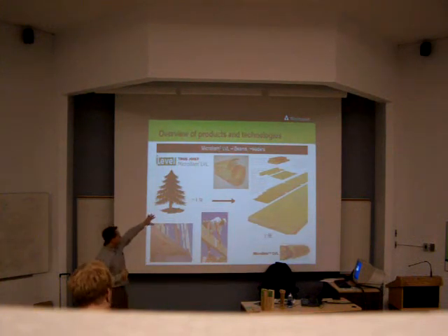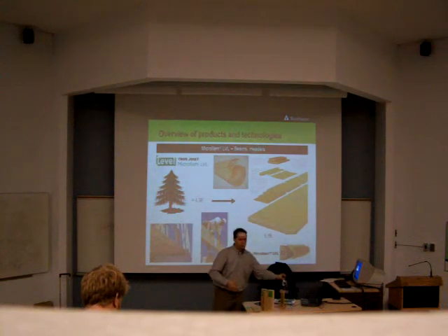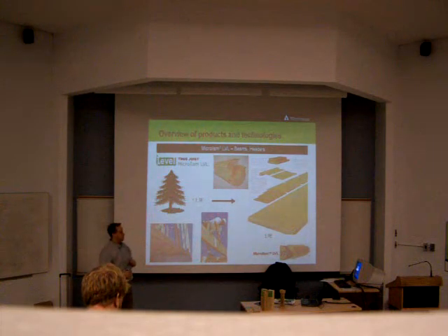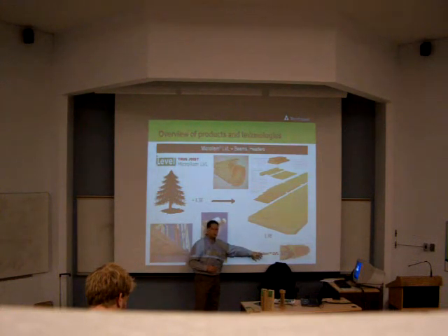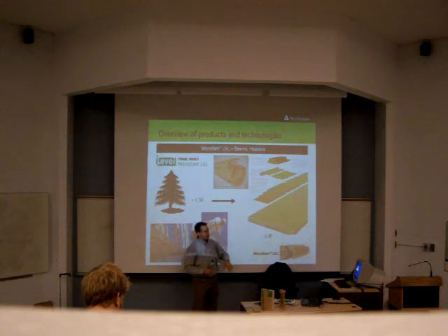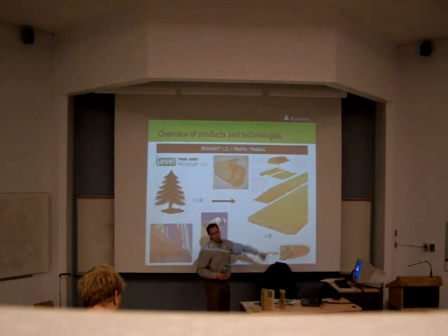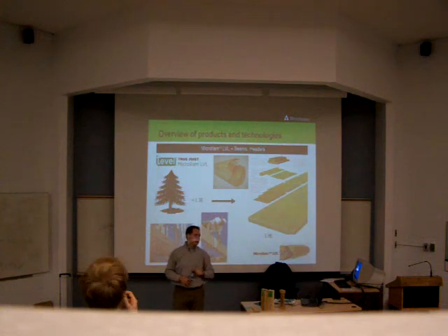So we take trees to make Microllam or LVL. We take trees, kind of like fir and grades or species of trees like that are generally 1.3 E in that range, and we make a 1.9 E product. Okay. The yield is a little bit less. We saw 76% of all of it with timber strand, and this is 52. It's lower because when we start peeling a log, the first few laps around the billet never come out as perfect, nice sheets of wood because there's branches, there's bark, there's trees a little crooked. So it's never perfect veneer.